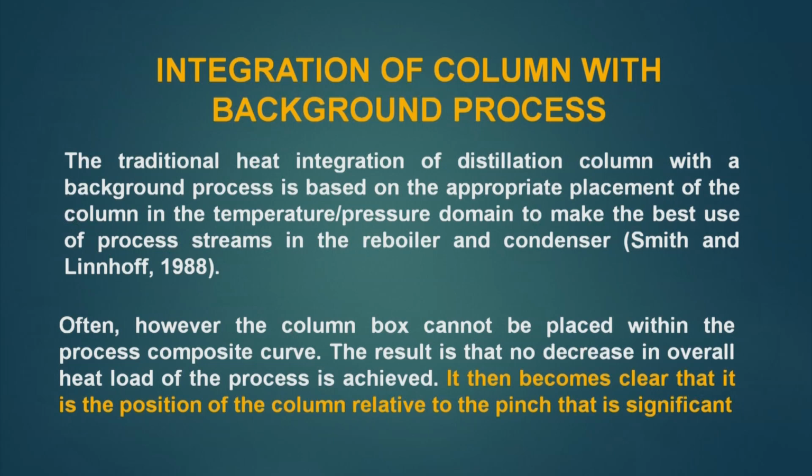It then becomes clear that it is the position of the column relative to the pinch that is significant. This we will see: whether placing the distillation column above the pinch will benefit, or below the pinch it will benefit, or across the pinch it will benefit. So, we will see where the maximum benefit will take place, and accordingly we will decide a rule where to place the distillation column with a background process for integration purpose.